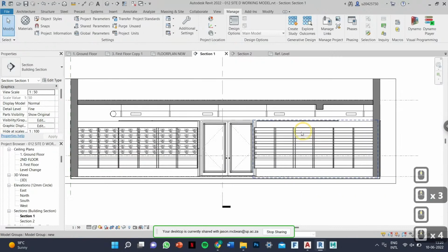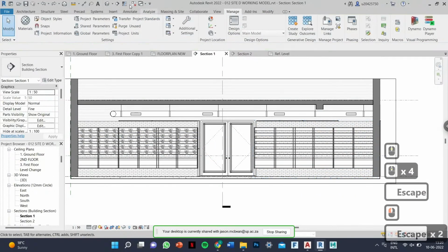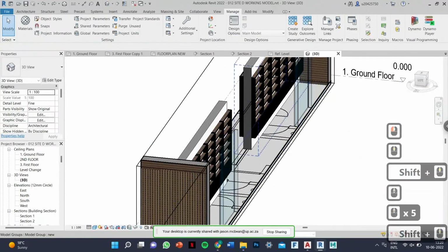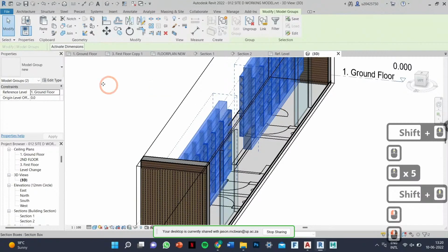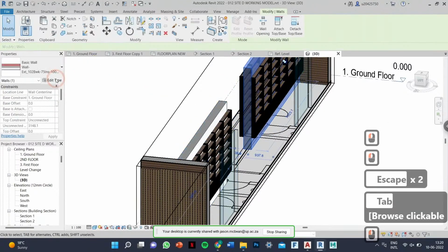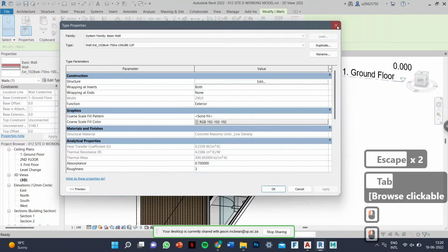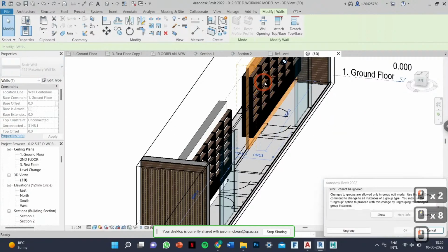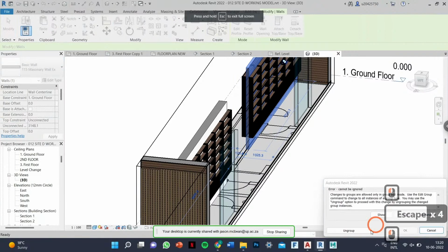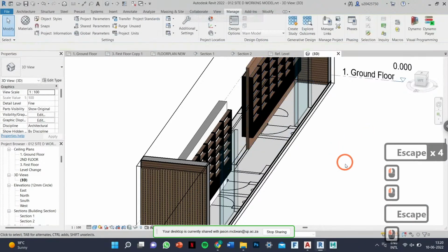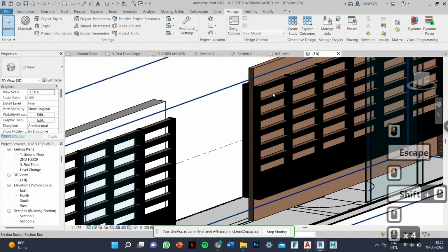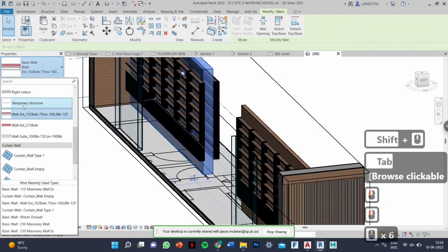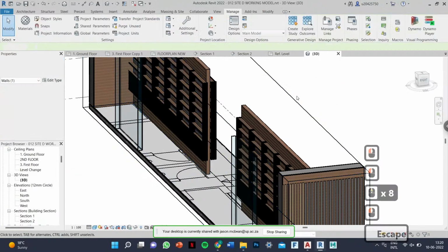Likewise with this thing, I would put that information in. I wouldn't go and waste time. Technically in 3D, there's nothing there. I would make this a thin little stud wall as well. I would duplicate those and make those stud walls, a thin internal wall. These walls we don't use. I'd make this a 115 existing wall, and group, that's fine. And you can change the material so it's grey. That to me makes more sense, because to build that wall, that's going to be, okay.